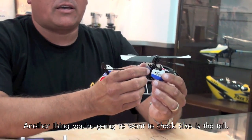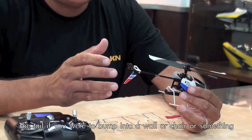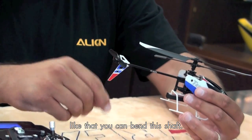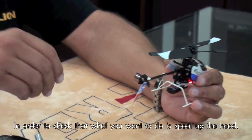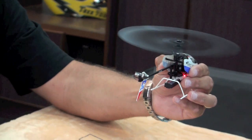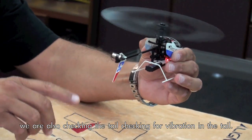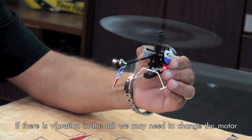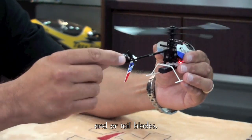The other thing you want to check also is the tail. The tail, if you were to bump into a tail, or should I say a chair or a wall or something like that, you can bend this shaft. So in order to check that, what you want to do is just basically spool up the head. We check the head, and now we're also looking at the tail here. We're checking if there's any vibration. If there's vibration in the tail, there may be a need to either change the motor and or the tail blades.